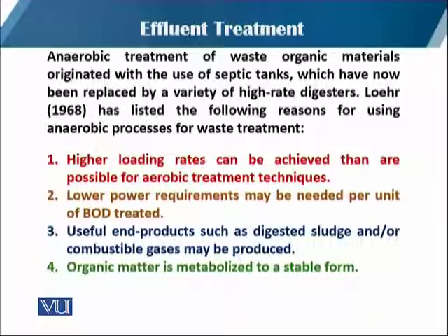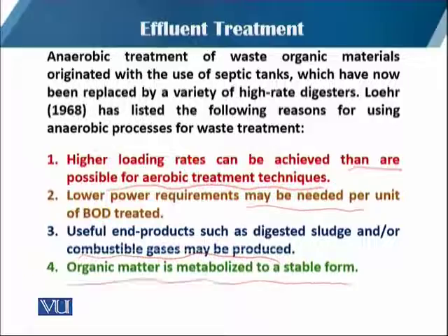Number 1, a high loading rate can be achieved, more than is possible with aerobic treatment techniques. Number 2, lower power requirement may be needed per unit BOD treated. Useful end products such as digested sludge or combustible gases may be produced, that may be methane, that may be hydrogen. Organic matter is metabolized to a stable form.